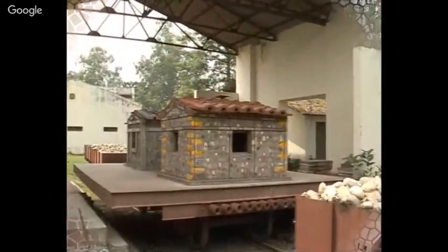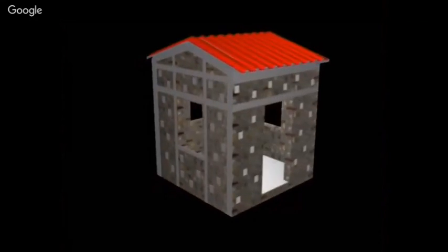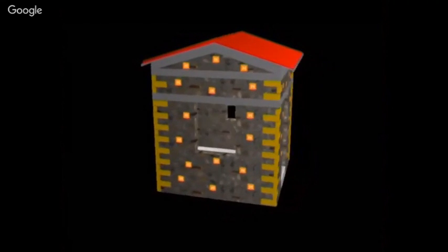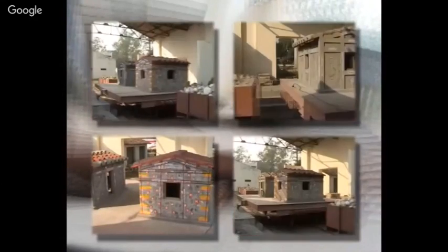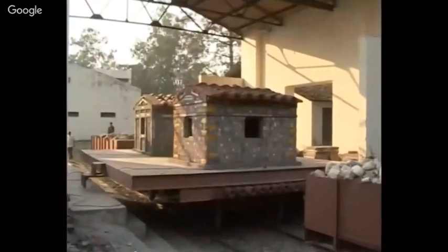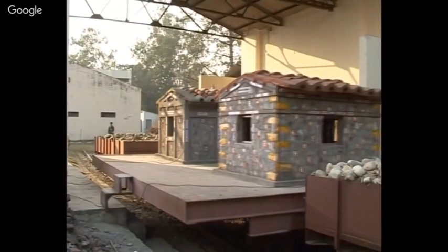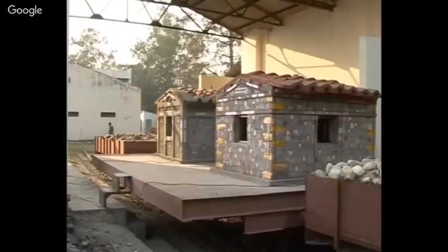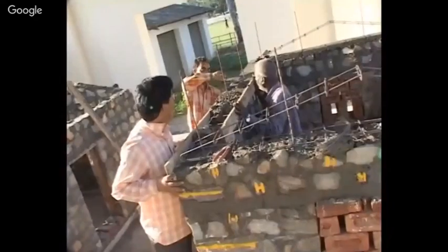Now, on the shake table, we have two similar models. These two have the necessary strengthening features, retrofitted in one while built in the other. For the first shock, the loading wagon is released to generate a low-intensity earthquake. With each subsequent shock, there is a gradual increase in the intensity. It is clearly visible that both the models are showing the desired results. Even after a severe intensity of simulated earthquake loading, there is absolutely no damage in either of the models.